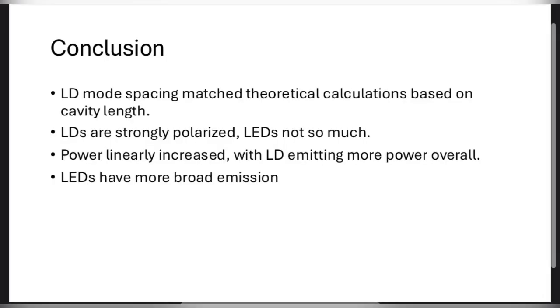In conclusion, the LD greatly differs from the LED, having a stronger polarization, more power, and a more narrow emission. We were also able to find mode spacing for the LED using theoretical calculations that lined up very well with our actual values.